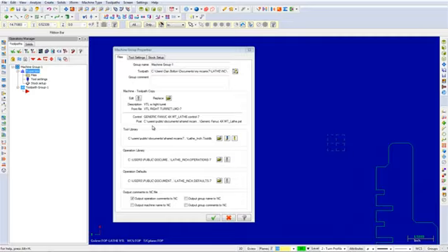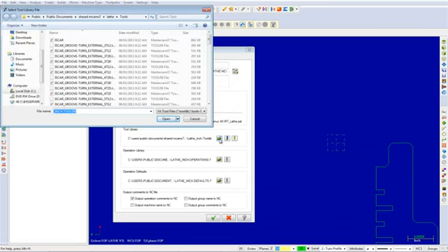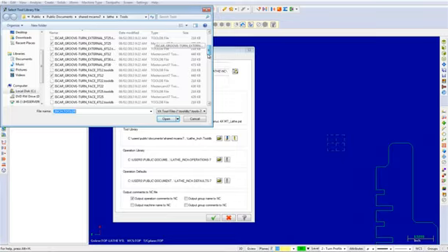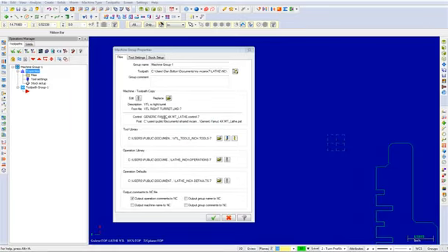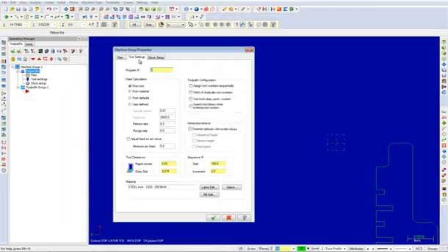From here, select the Open button in the Tool Library area as shown. Select the VTL inch tools and then select Open. Now select the Tool Settings tab. Input a program number of 9 and enable the options Assign Tool Numbers Sequentially and Warn of Duplicate Tool Numbers.